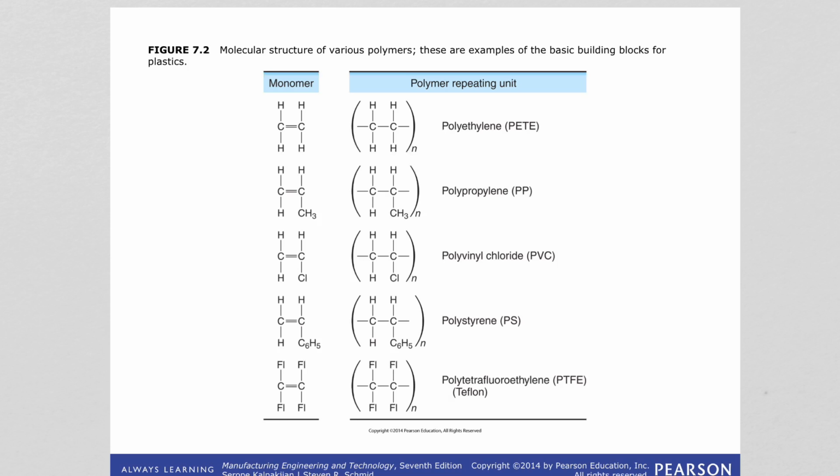So we are seeing the Teflon structure. As you can see, the main backbone, the main chain, is a carbon-carbon bond, okay? And as you see, all polymers are named with poly, right? So many repeating units, and the side atoms that are attached to the carbon are changing. Depending on that, all those different properties can be achieved by different types of polymers.